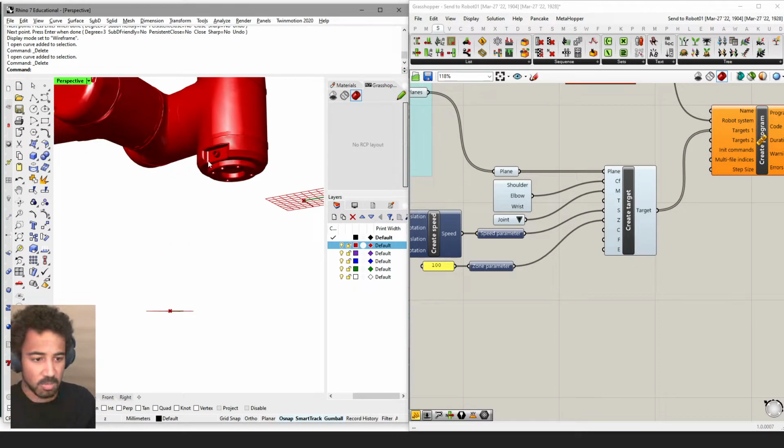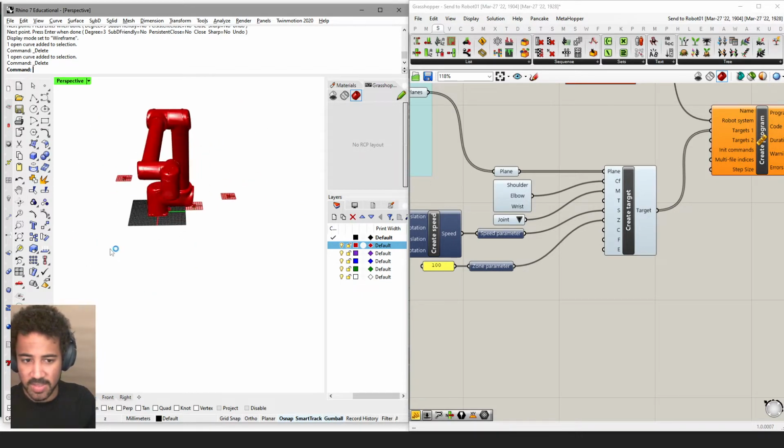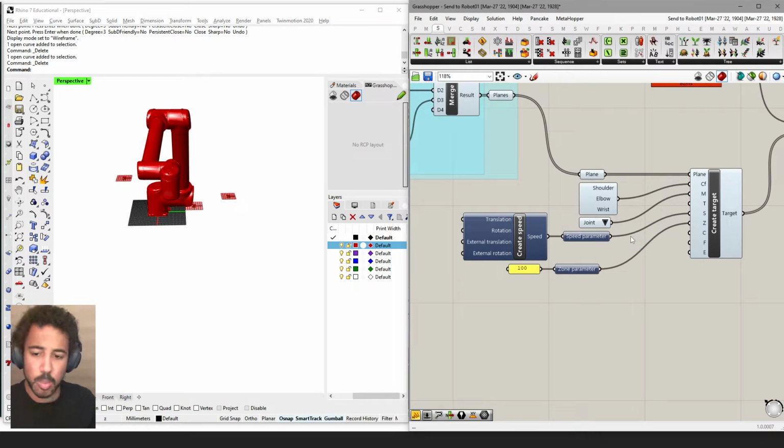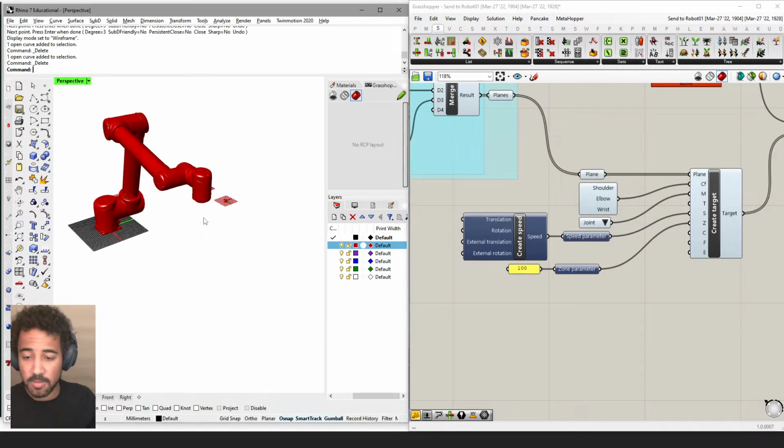I hope I can explain how this all comes together and why this is necessary in our robot program in this video. Whenever we're using universal robots or any kind of industrial robot, the robot itself is just a motion platform. The robot itself doesn't have any functionality, and the functionality comes from whatever tool we add to the robot. This might be a gripper, this might be a nozzle of some sort to extrude, this might be a drill or a milling spindle to cut something, and whatever we add to the robot that then gives us the functionality.